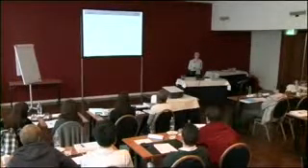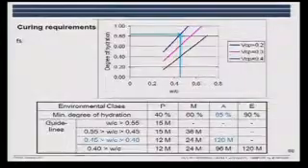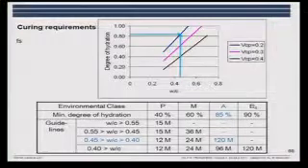It's said in some of the literature that if you have less than 20% capillary porosity, it's disconnected. That depends on at which level you're looking at it. But you can see that if we, for instance, look at the requirement here for extra aggressive, we will have less than 20%.